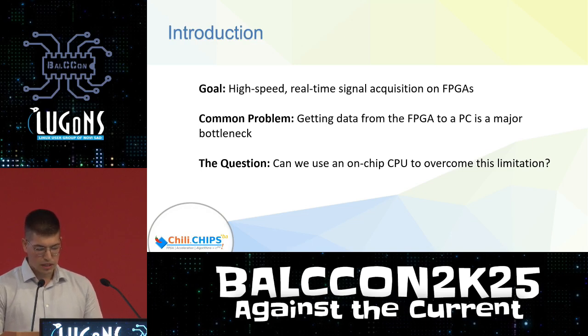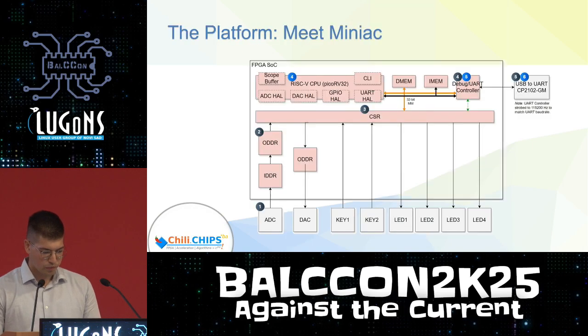So the idea of the Miniac is to snoop around over the FPGA, see what the ADC is sampling, then send it via UART to our laptop, for example. There we visualize the samples, recreate the signal from the samples, and plot out the frequency spectrum to see what frequencies we're actually dealing with.